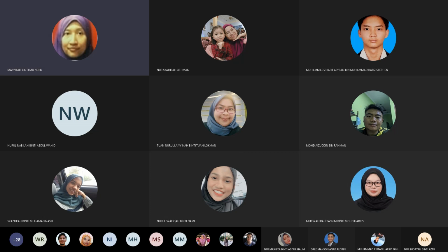Okay, look at slice number 5. Here slice number 5, we have divided half, 1 meter left, 1 meter right. So this is the position of W5. Look at alpha for W5. From here, O, until the baseline of slice 5. So we take it from here until we meet the baseline.